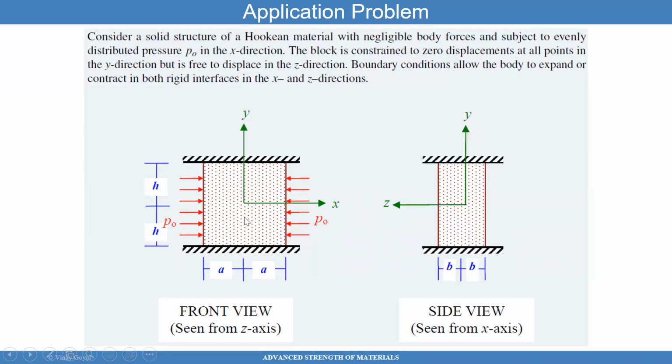Meaning that if I look at the deflection of this point, if that moves 0.1 inch, which clearly doesn't, I mean, you'll see here that the center line should stay in the center. Kind of makes sense. But if I look at the deflection, say here, and that moved 0.1 inch inward due to the pressure applied, what we're saying is that the deflection here, here, here, here, all of them are likely to move 0.1 inch in the X direction. So it does not depend on Y, and it does not depend on Z, meaning the deflections are uniform through the thickness of that solid plate.